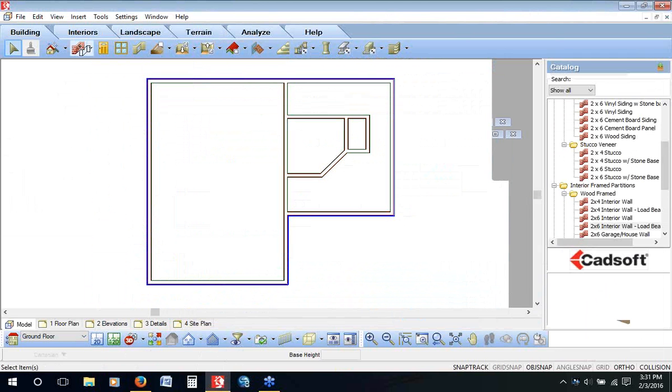We then started drawing walls. And when we started drawing walls, I first started by right-clicking and using our Insert by Baseline method. Remember, that drew a single line diagram and allowed me to type in exact dimensions so all of my wall lengths were accurate right from the get-go. Then we started drawing walls by picking points, looking for our object snap. We also used our offset option, so I would type in an exact dimension I wanted to be away from a corner. I turned off ortho, so I could draw up on an angle. And then I duplicated walls as well.